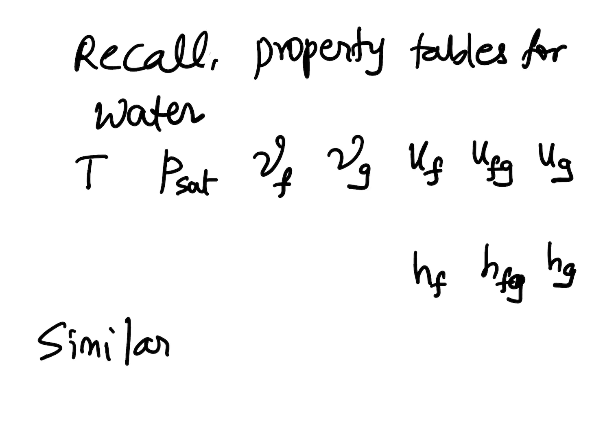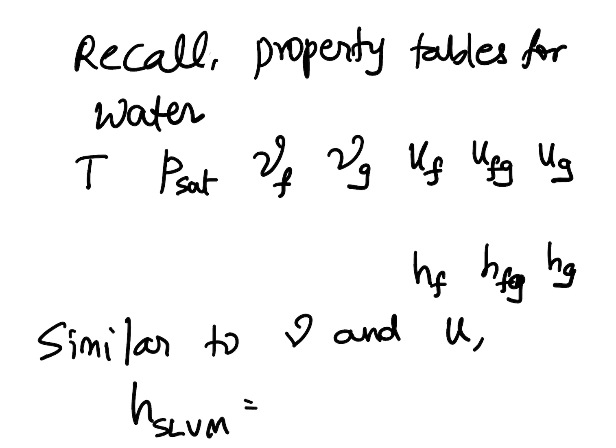Similar to specific volume and internal energy, h for a saturated liquid-vapor mixture can be calculated as x times hg plus 1 minus x times hf.